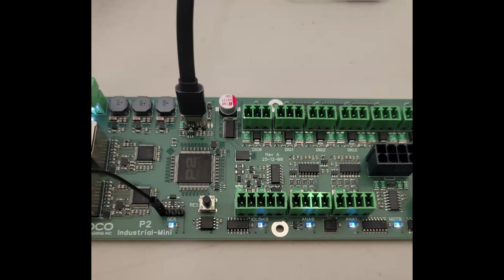And that circuit with the cap and the Schottky, it sounds like what you're describing is a snubber circuit. Is that right? Right. Yeah. Well, the way I look at that circuit, it's so that when you get back EMF on the H bridge, it can dump. It's going to have the effect of lifting up the 24-volt supply that the H bridge uses.